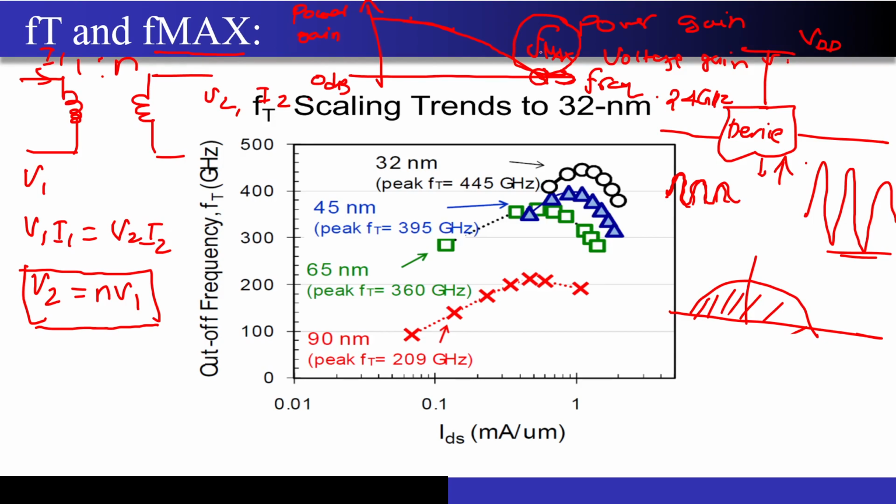Any power gain. But can we hit this number? If you look in the literature, nobody has designed a circuit exactly at Fmax. They at least operate close to Fmax by 3 or Fmax by 2, max. This is a very, very difficult design. If you refer to the latest research papers, you will see a few people have been designing circuits over here, but the amount of effort that is required is absolutely crazy. So basically, a power gain of 1 can only be possible at Fmax.